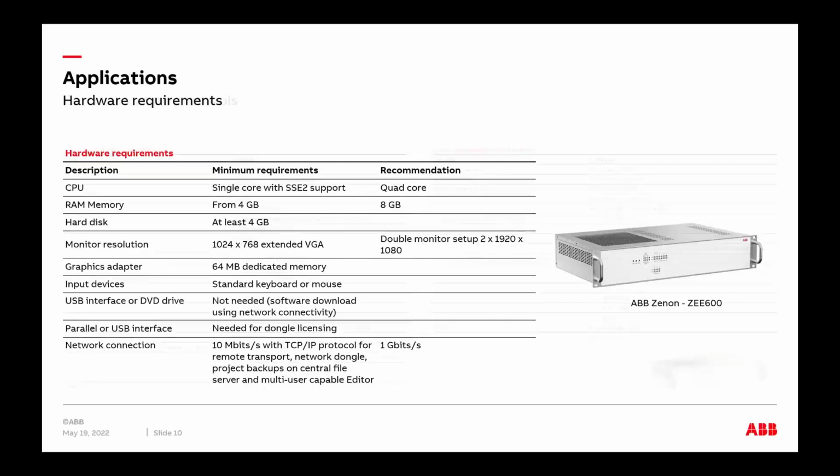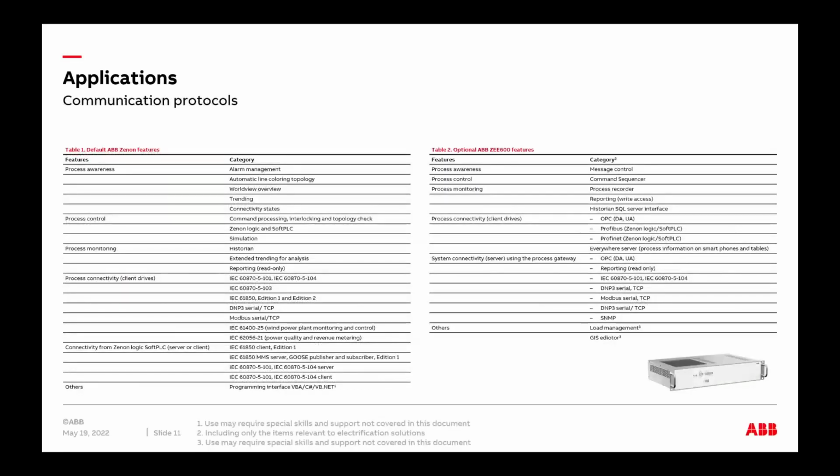Now, when we talk about the software, you need to care also about the communication protocols. Some systems can handle over 300 protocols, but you need to know what protocols you have. If you have all those devices, if they are okay with 61850, they can support it, you're good, use that.